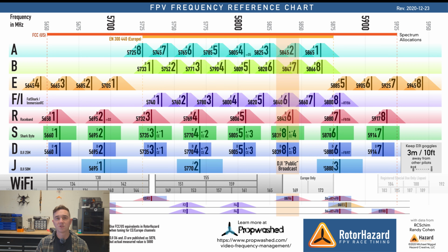So for us, when we talk about channels or bands within FPV, there's certain bandwidths at certain frequencies assigned to certain channels. What this allows us to do is, as we have multiple pilots, we can assign different channels so that we're not getting other people's video feeds. For analog, I always recommend using the race band. The race band was set up so that you can have a lot of different pilots, 8 channels that don't interfere with each other. Sometimes they do, depending on power outputs and other stuff. You can get interference, but we'll get into the propagation in a bit.